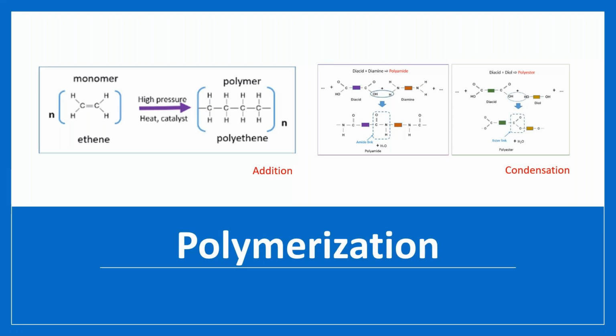This is important to note because if we're giving off the water, and we put the water back in with a lot of heat, we can cause the process to go in the opposite direction. Known as hydrolysis, if we put the water back in at elevated temperature, we're going to start to break the chains apart instead of extending the chains like you would with the polymerization process. So the materials made via condensation polymerization are materials that we are concerned about moisture when we go to process them.